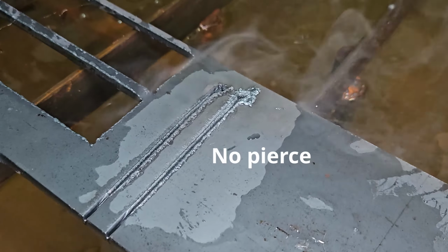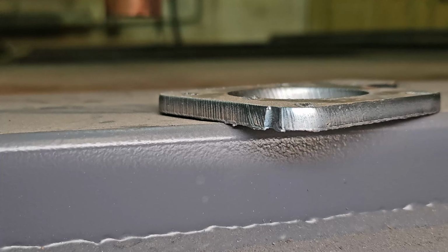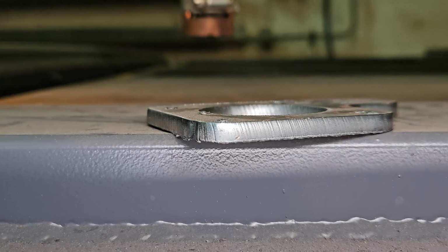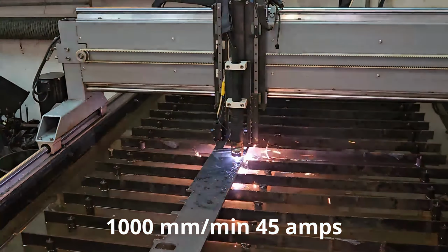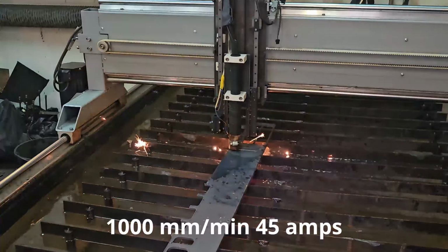If you are cutting too slow, the raging beast has too much material to eat, which makes the cutting edge uneven and overheated. Cutting too slowly also causes forming of excessive dross, because of the extra material which is being removed. If your cutting speed is too fast, most likely it will end up not cutting at all.